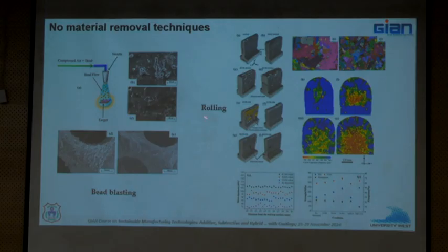This is another example. Just roll it with abrasive media, get substantial improvement sequentially in roughness. You can see you get a lousy part to start with, lousy looking, but near net shape, and then you want to remove the roughness.